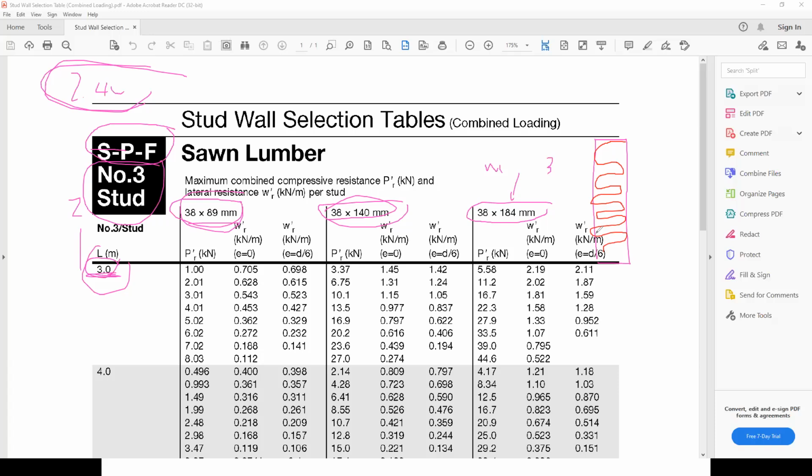So with the 2x6, you might get some architects who want to put more insulation in the wall. In other words, they want to create a bigger cavity and they're going to tell you to use a 2x8, and therefore you would be using this table here. It's the architect that's going to tell you how much of a cavity he wants you to create in your structure so that he can insulate and get the right R factor for his exterior walls, okay? Because he has to obey the energy law that's in force, and he has to make sure that the R value of his wall meets the R value dictated by the law of conservation of energy.